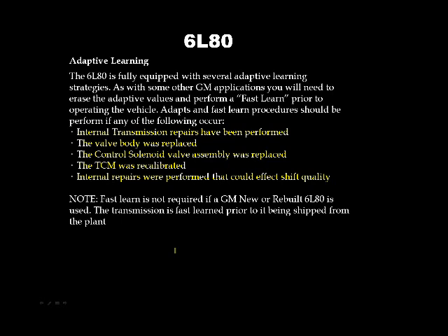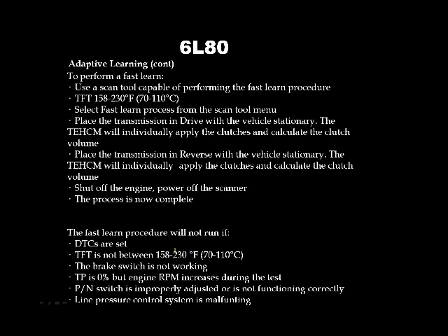So that information is stored in the TECM during the testing process of the transmission itself. But you've got to rebuild from some other source. You're going to end up obviously having to go through and do the relearn itself. The relearn is actually fairly simple to do. Not a real razzle-dazzle thing.